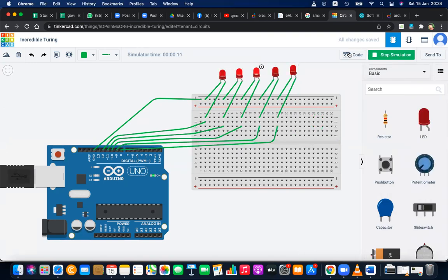Can you see this? It's the Knight effect, right? So everything can be programmable. Now you can understand everything can be programmable on this board. The problem comes because there are no resistors. That's the reason. So better you connect these two resistors.